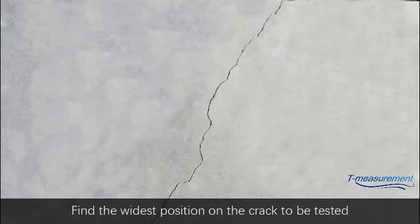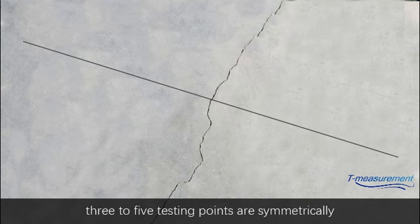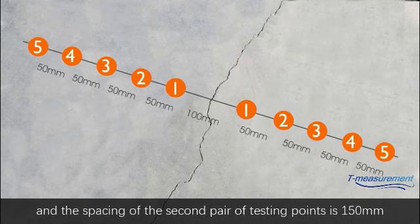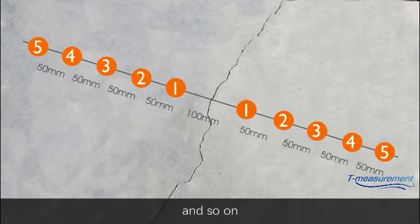Find the widest position on the crack to be tested and draw a line across the crack. 3 to 5 testing points are symmetrically arranged on both sides of the crack. The spacing of the first pair of testing points is 100 mm, and the spacing of the second pair of testing points is 150 mm. The spacing of the third pair of testing points is 200 mm, and so on.